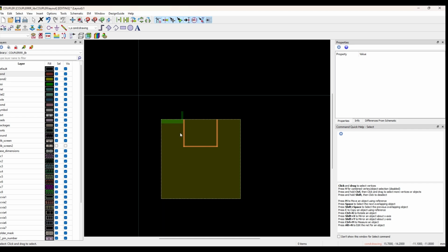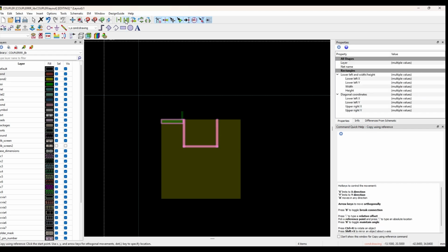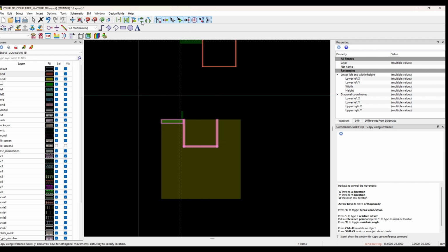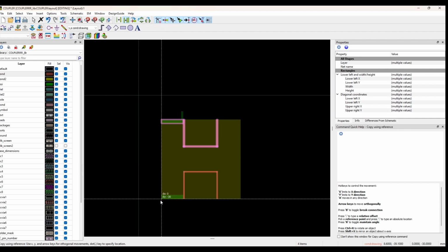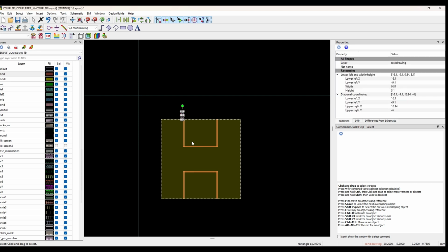So what is the best way in ADS software is you can directly take the other, select all these, copy from one single position, and just press this button to mirror over the x-axis. As you can see, in 1 second I could do the replicate one. It is as simple as that.